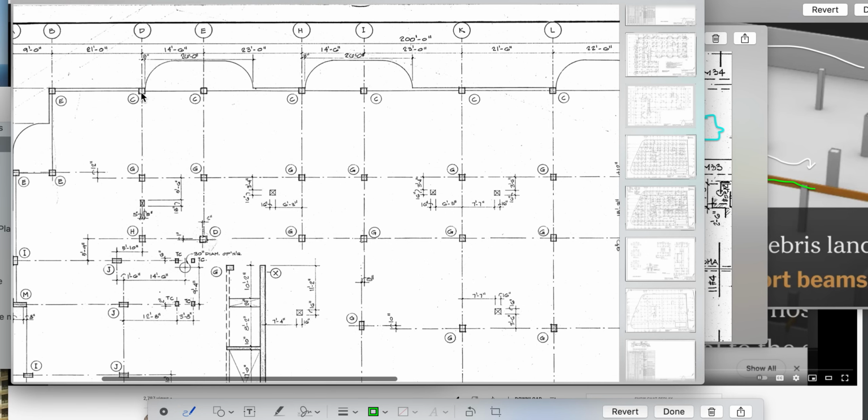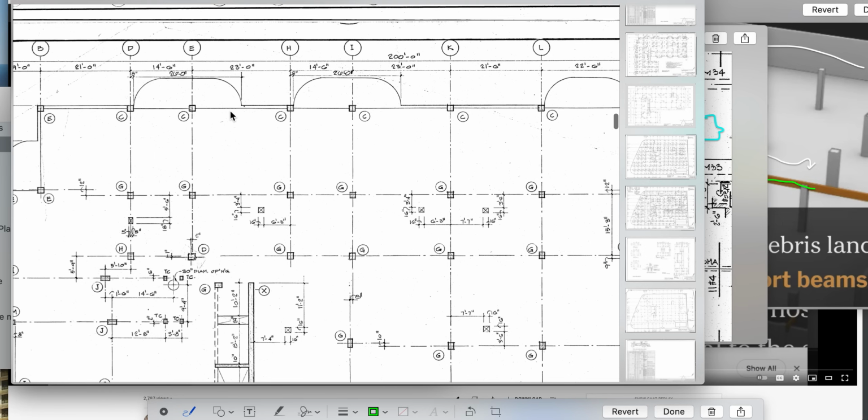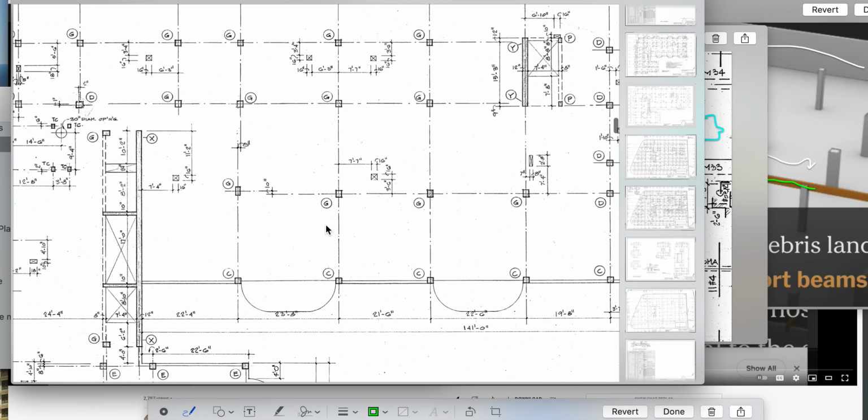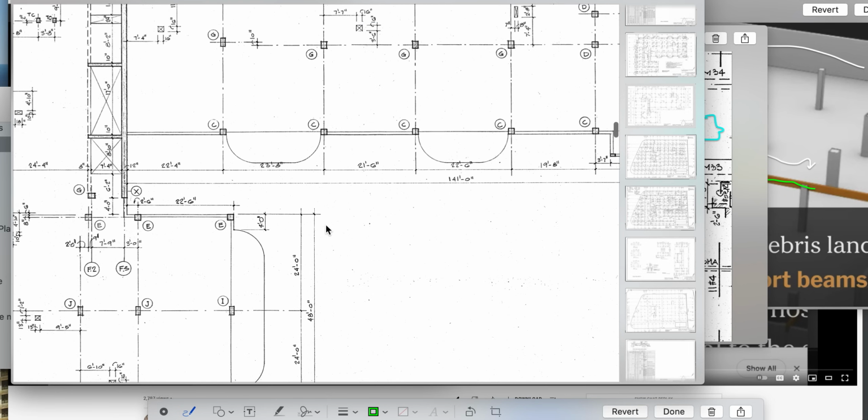And then is this the last one? Yeah, it sheared somewhere about here, which makes sense, right? The columns, and there's some floors that stick out a little bit. And this is gone. Half of it's gone. Half of the porch, half of this is gone, which makes sense, right? Because of the reinforcement ripping out because of the way they overlapped it. And that gave us that new shear plane.